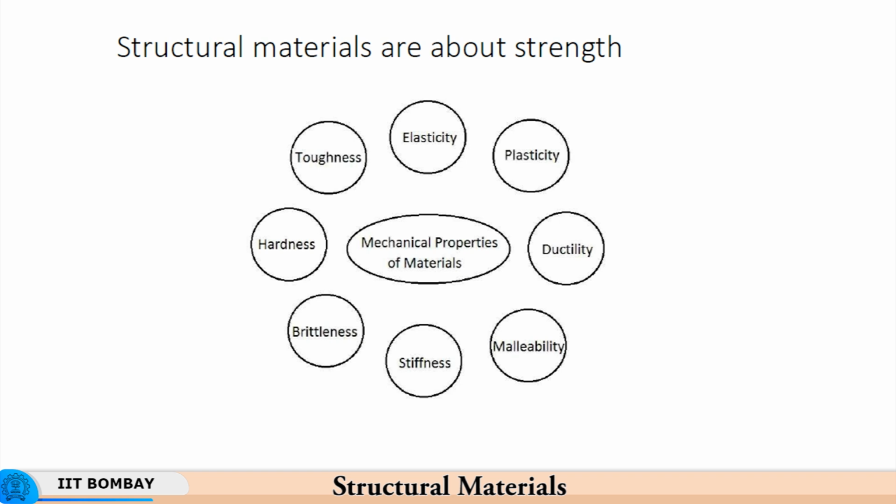So, that is elastic. In case of plastic deformation, the change of shape remains permanent. So, if I have applied a sufficiently high load, so that it crosses a limit called the yield point, then whatever deformation you might have given it remains permanent, and it is not retrievable.